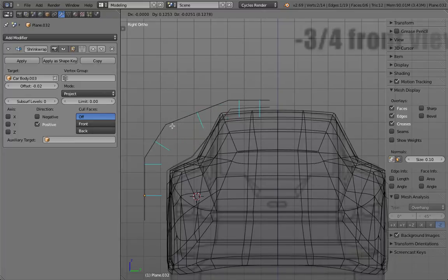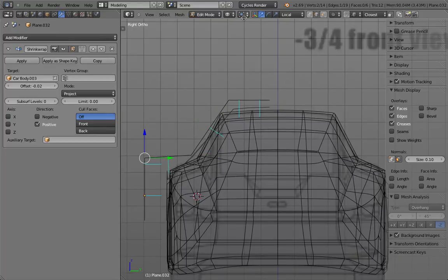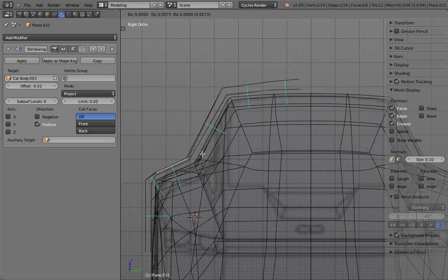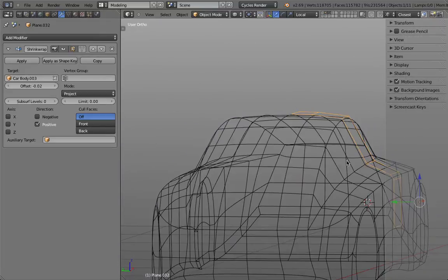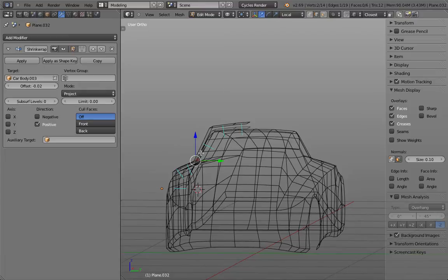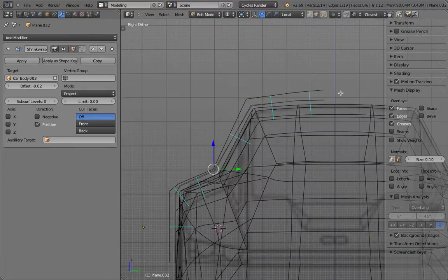So all we need to do, so you see like the moment I, for example, make those faces look more not tangent, perpendicular onto the surface it should be projected on. So in best practice, all I want is that actually the objects are nearly parallel to the surface I should project onto. I get very good clean results. So now for the software, it is really very easy to understand how, for example, this band should be projected onto my surface.